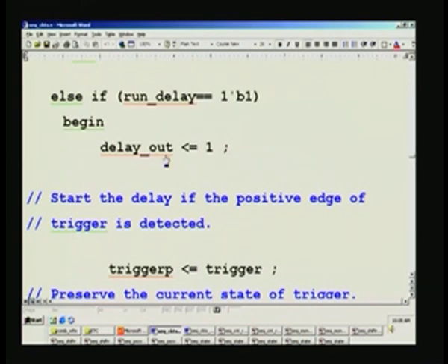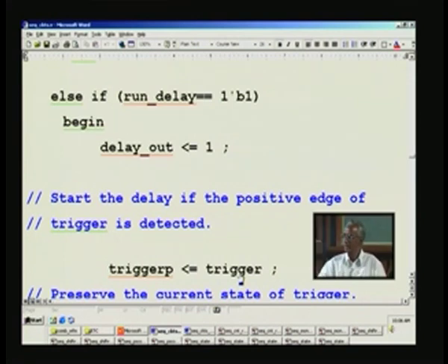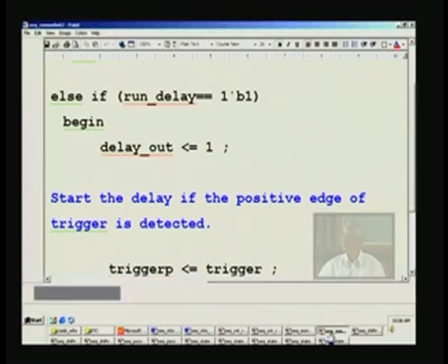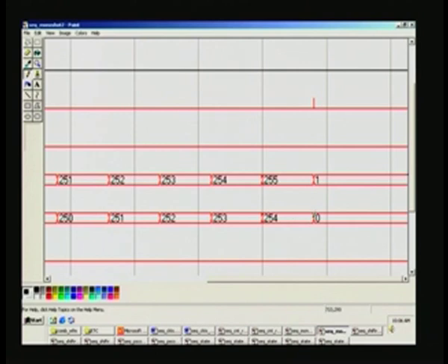The reason being that when it touches 255, in this case you would have very easily seen 255 clearly for one complete cycle. In this case what we had seen here is 254. In the previous case, had you implemented that one, after 254 it wouldn't become 0, it would go to 255 and only next go to 0, because the counter reg is activated in the present clock cycle, which is taken into consideration only on the arrival of the next clock.